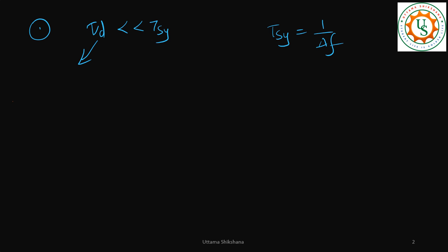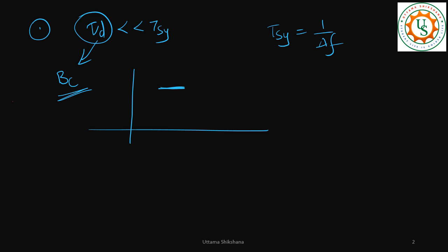What about this one? This is a delay spread, right? In the frequency domain, it is related to coherence bandwidth, the bandwidth over which the channel frequency response is flat, right? So definitely if we have the channel response flat for this much bandwidth, definitely the subcarrier spacing, whatever we consider, should have a width much smaller than this, right?